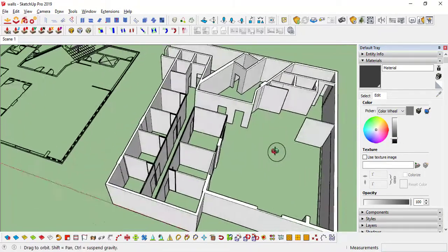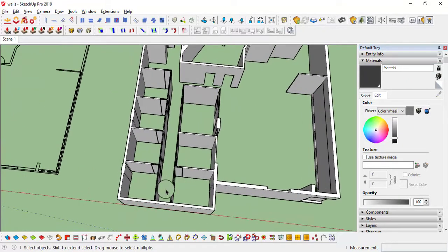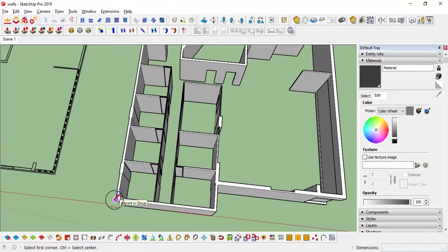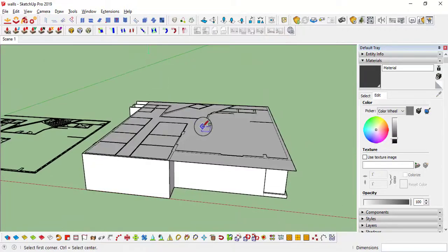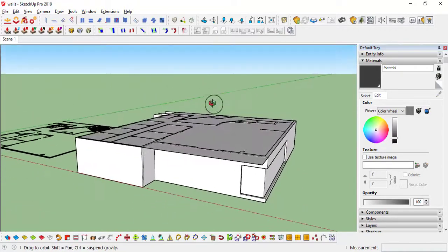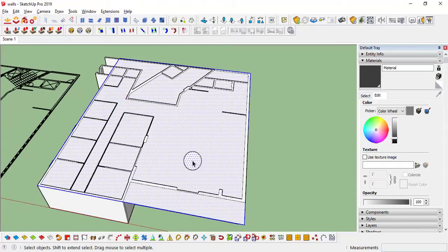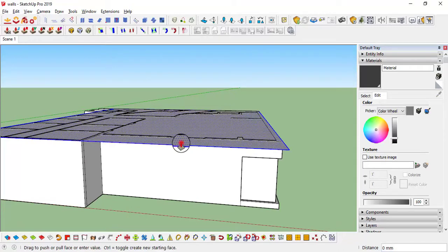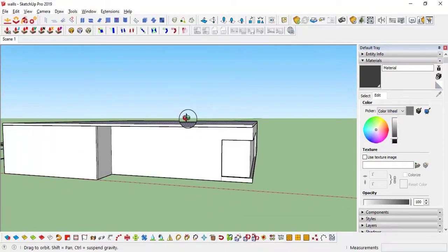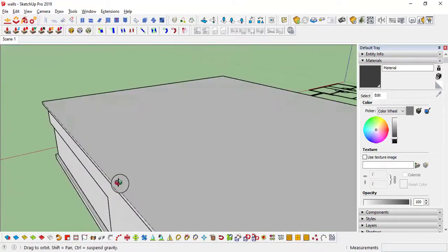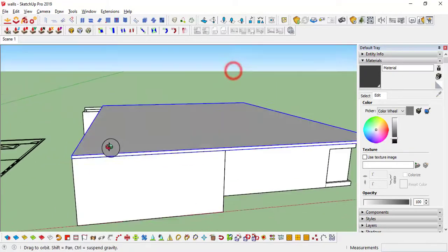Okay, so I'm not going to make that. By the way, we need the flooring. Simply, this is how you can make the floor: R for rectangle, and I'm just covering like this. Why rectangle? Because there's no need to track each and everything, but we will track the internal part. So push pull 6 inches. Why? Anyway, we are taking only the internal, not the external. So again, we don't need this one, so make the group with M control.